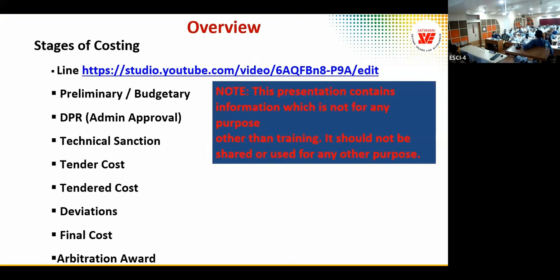Should technical sanction be accorded for the whole project or component wise? Whole project, sir. I divided the whole project into 10 sections. For example, section 1 is civil, earthwork, site clearing, initial mobilizing, site enabling, and all that. Section 2 is civil structure, substructure and superstructure. Section 3 is civil masonry, finishers, and all. Section 4 is E&M, electrical, mechanical. Like that, we divide sub-estimates in the estimate. And technical sanction is separate for each section.